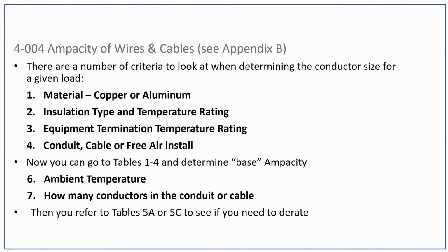I find it's a little bit confusing to start like this, but it is the first fundamental step of looking at the max ampacity, and then we'll look at other rules as to why the ampacity gets reduced, because the termination temperature rating is usually about 75 degrees.